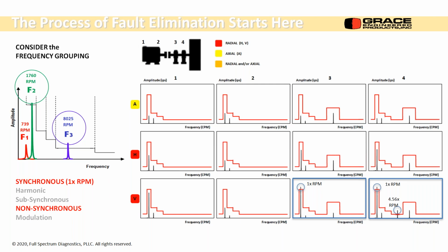It's just an extension of the rotor bars, but they aren't really pulsing anything. They're just pushing air through. Your plastic fans on other motors, they're light and there's really no vibration. You know, they could fail and you wouldn't know it. You'd get an over temperature probably, but they really don't have a lot of impact on the vibration.